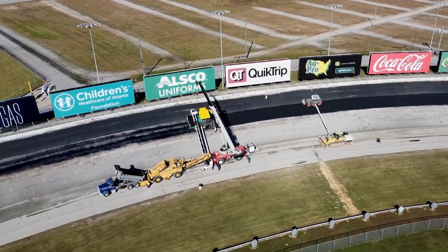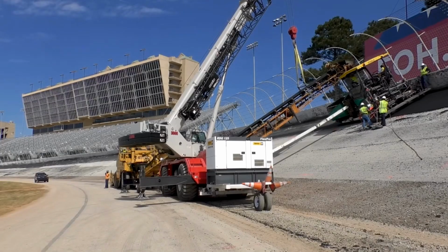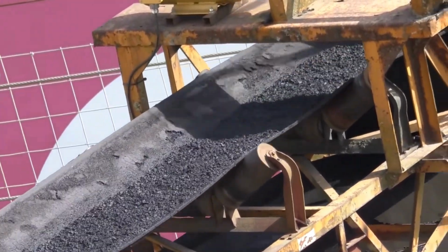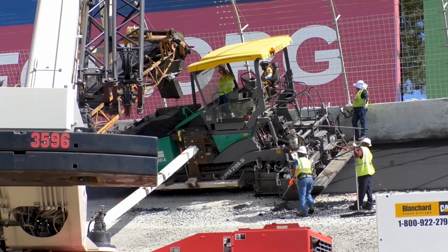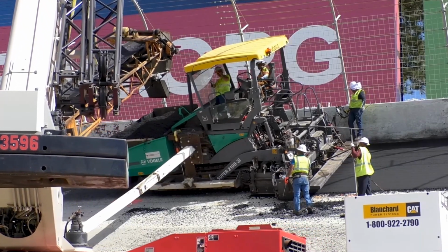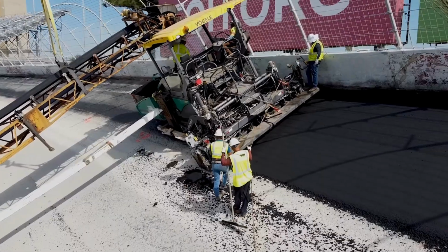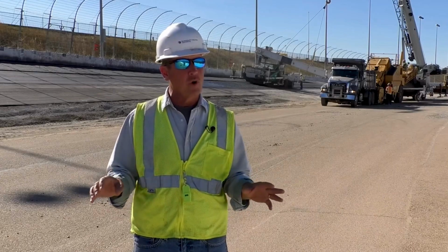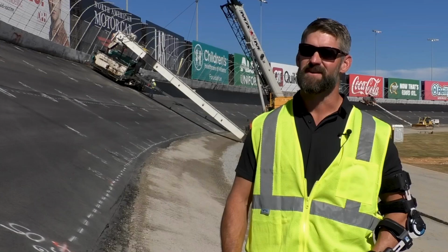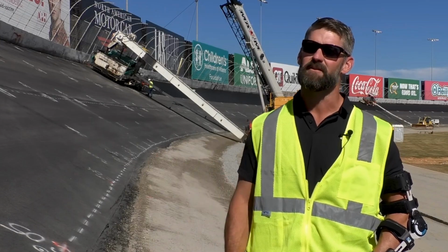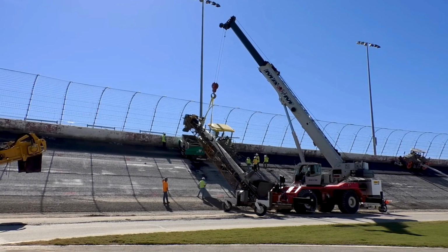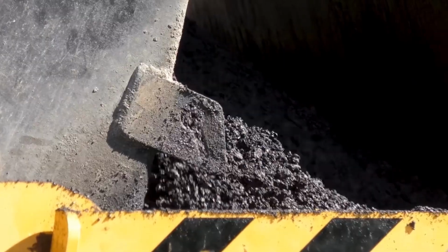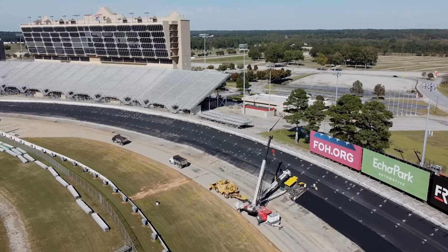Atlanta Motor Speedway's new 28-degree banked corners have amplified many of those challenges, forcing some quick thinking and adjustments to keep the project moving forward. We fabricate something almost every week to help us and come up with new ways to make it better, make it easier. For one example, the hook point on the paver, it totally didn't work. We had to make some modifications to the equipment because it wasn't holding the paver up there. The paver wanted to keep coming down the slopes. We moved it 9 inches, and that fixed it. So it's just a small 9 inches. Thanks to speedy solutions like that, paving is well underway.